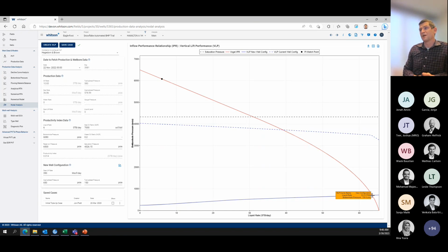But in general, there are times where we're looking at installing tubing, or maybe considering annular gas lift versus conventional gas lift, those types of decisions where we need some idea of what the well could produce with various forms of artificial lift and various operating methods. This is going to help us quite a bit to run these numbers more quickly.